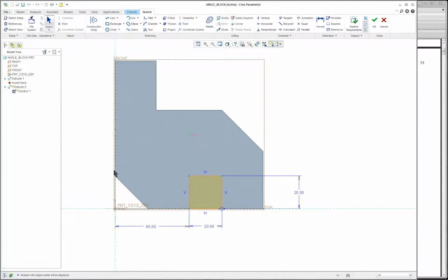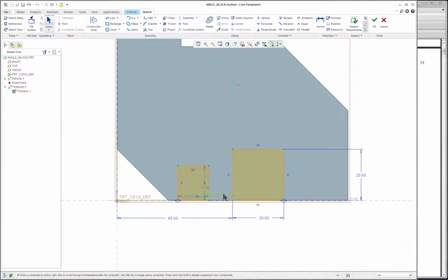So we're using the left-hand edge as a reference and the bottom as a reference. Simply right mouse button, corner rectangle, pick two positions, and then add the appropriate dimensions. When you put in a feature, it doesn't necessarily put in the correct dimensioning scheme that you want. So let's put in another one here. So you can see this one dimensioned from over there, and then you have your width and your height, and those are okay. But this one here, I would have to change that dimensioning scheme and go from the reference over to the edge if I really wanted it dimensioned like that.